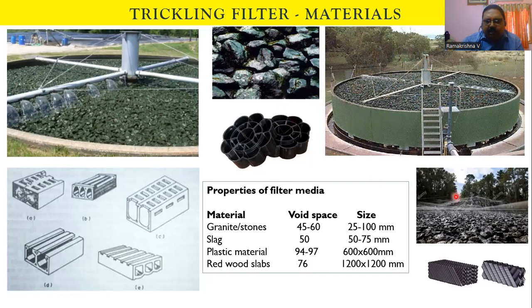And now you see here, the under drain systems are provided. The water will be collected from the bottom openings here, and the water falls from the filter bed into these small openings, and then passes through the wide openings provided at the bottom, which are inserted at a longitudinal slope towards this particular direction, right?